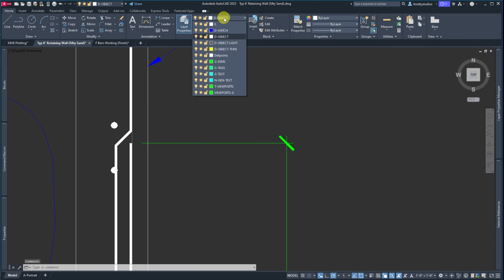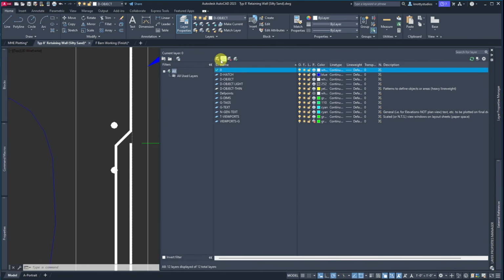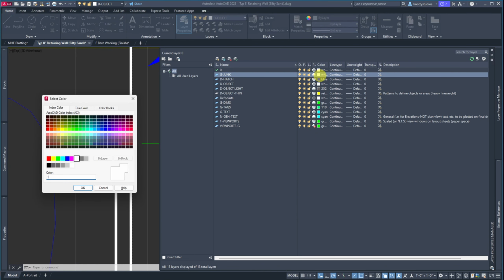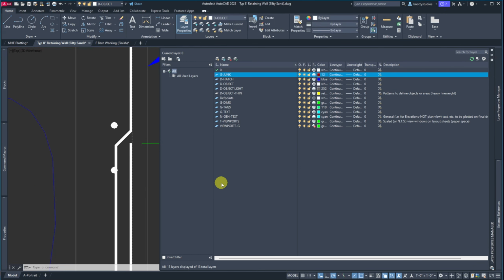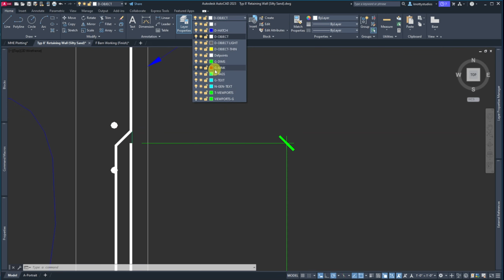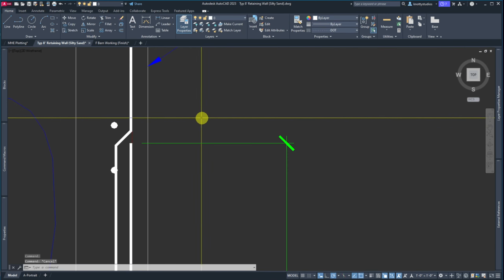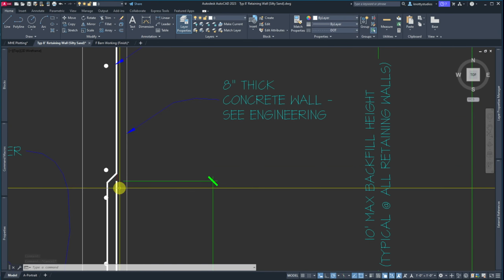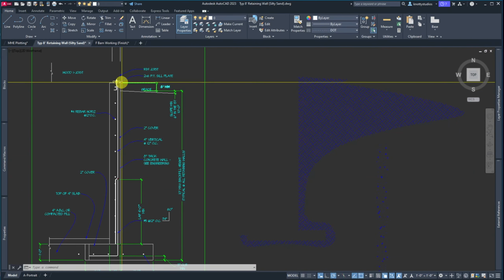And if I want to, I actually should have it in here, and it's not. I'm going to put it in. This is a general layer in my layer set, so I'm just going to hit new. The layer is called G-junk, and the color is 12. This is just a layer for your own drafting purposes, if you haven't been watching my videos. It won't print, so if you accidentally leave it there, it's not going to print. So now it's there if we want to dimension to it later.